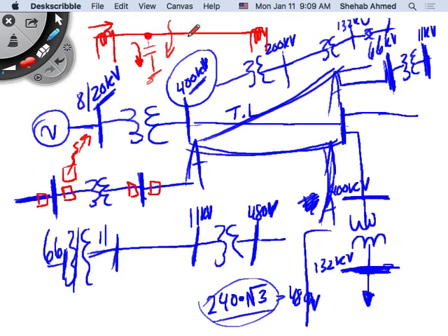But if these 2 points are very far away, how would you deal with this? Add a communication system. Have a radio here talk to a radio here. So typically we have in the power system microwave links or fiber optic links. And that's why it's important for communications engineers to understand how a power system operates, because they're very critical. The idea of protecting a power system cannot happen if you don't have these radio links or the fiber optic links that are used to protect the system. So there's a lot of communication engineering work for people working in the utility.